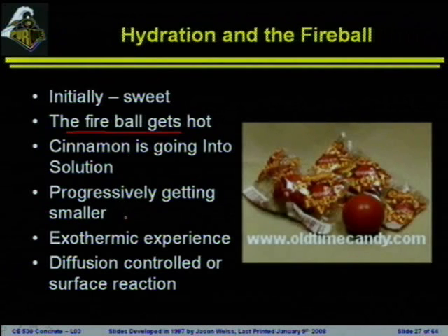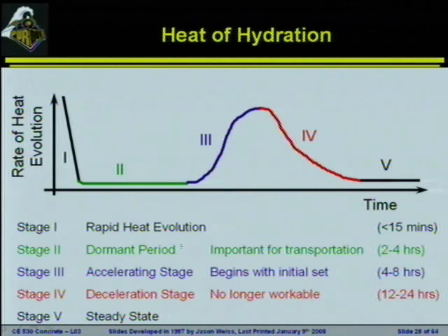During this time, the fireball is going to progressively get smaller. As the cement particle reacts, it will progressively get smaller, but the hydrated products around it will cause these particles to start to grow together, until, especially in the cement system, the surface reaction starts to give way to something more like a diffusion-controlled reaction.